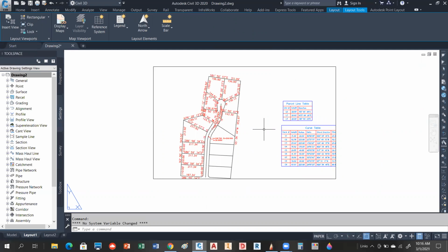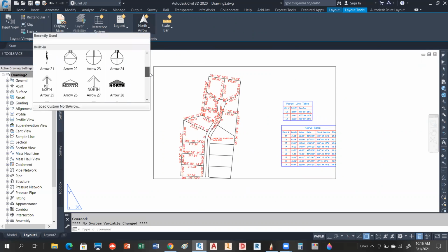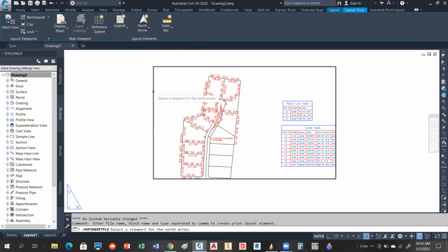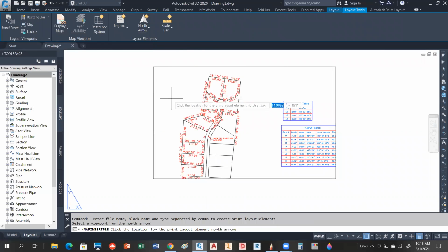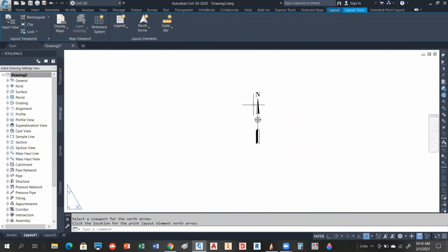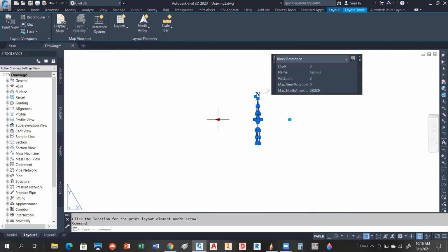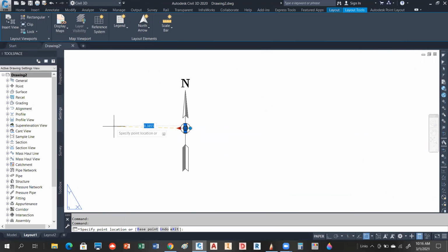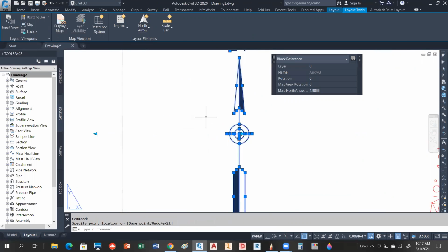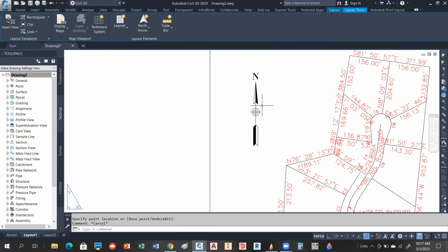If you remember, I showed you guys this the other day. I'm going to go ahead and add a north arrow here. It's the north arrow I like the best, I think it's the best one they've got. I'm going to click that viewport and generate that north arrow anywhere. And remember, it comes in very, very small. It doesn't recognize a scale. So you click on that block, and this will be your scale factor. You just probably want to generate it so you can see it. I think you could probably type in a value too, if you wanted to.